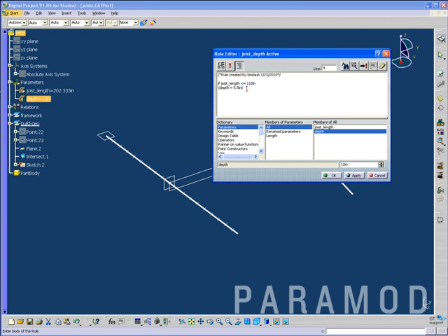And so we might just cut and paste this down here. But now we want to add something a little bit different. We want to say, well, if joist length is less than or equal to 110 inches, then make that a 2x6. Else if, meaning that if that's not true, then this happens.